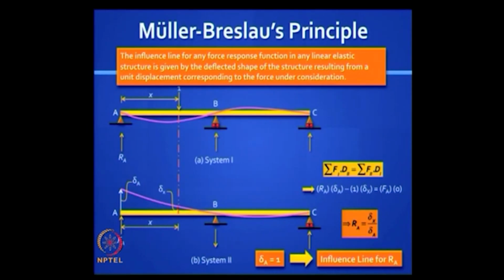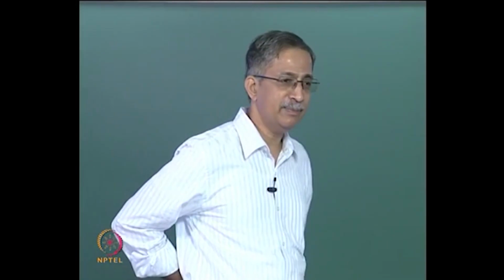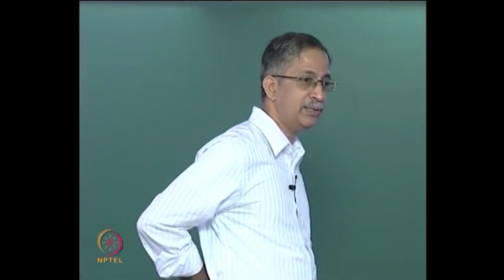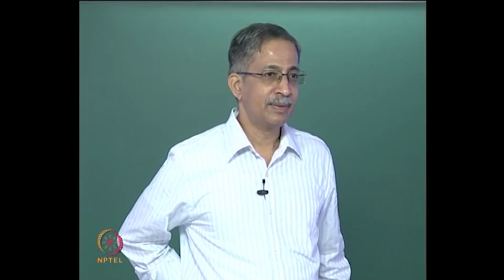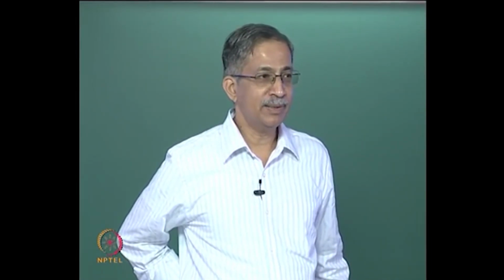And an interesting thing to note, and I want you to give me the answer for this, is that if the structure is just rigid, if it is statically determinate, the influence lines are always straight lines. If they are indeterminate, as in this case, they are not straight, they get curved. Why is that so? It's a good point to reflect over. Why is the influence line diagram for a continuous bridge made up of curved lines, but for a simply supported bridge they are all straight lines?